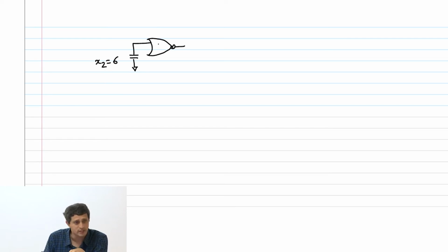Okay. So if this is a NOR gate and it has been upsized by a factor of K1, then what is the capacitance at the input? Unit gate gives 5C. 5 K1C is my total capacitance. So I can say 5 times K1 into C is equal to 6. Therefore, K1 is nothing but 6 by 5C.